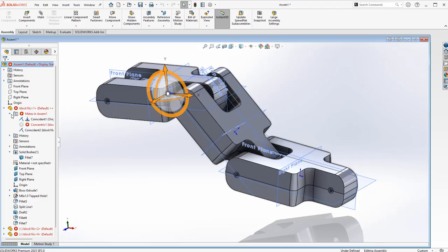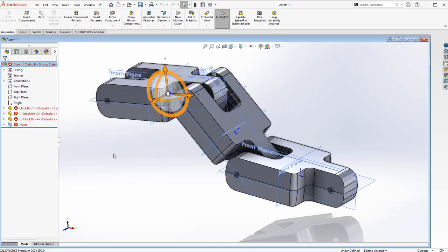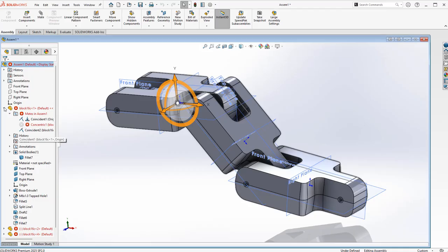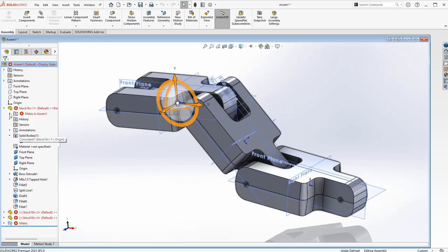I see, yep. So this is a relatively new addition to SolidWorks. In the past, 4,500 parts in an assembly would be extraordinarily, excruciatingly large. And what happens is you get so many mates underneath the geometry here that you can't figure out which one does what. So I'm not sure what release, but they buried them.